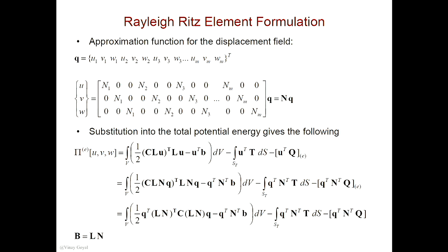You took the temperature inside the rectangle and interpolated it using the nodal quantities, T1 times N1 plus T2 times N2 plus T3 times N3 plus T4 times N4. And the shape functions have to satisfy the Kronecker delta property and partition of unity. These shape functions constituted the basis functions, and in essence what you have there is an approximation function.